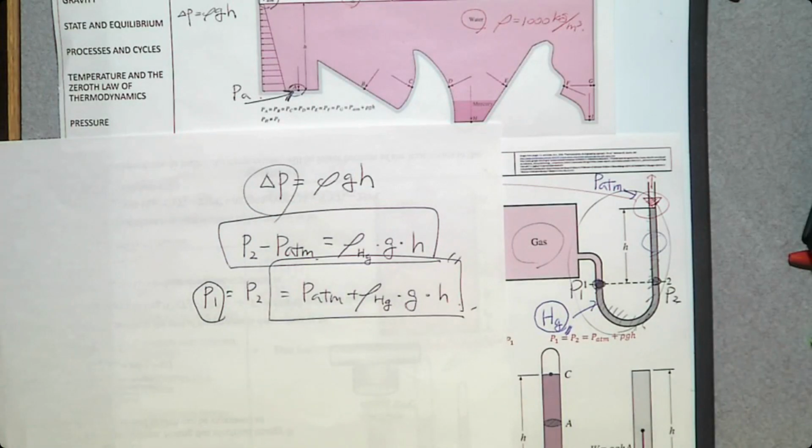So now let's talk about this gas. The pressure somewhere in this gas chamber, let's say this location. What is the relation between the pressure at this location and P1? P1 is greater than the pressure at this location. But how much? Very small. By rho g h. What is the density of gas? It's usually negligible, very small, right? So the pressure change in this gas chamber is negligible, right?